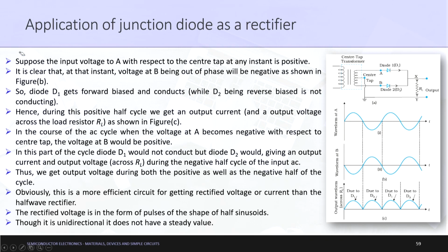So, basically what was happening till this point was that in the upward part it was positive, and if it is positive in this part, it is negative in this part. The voltage is negative in this direction, that means it is forward bias in this case, and it is reverse bias in this case. Correct. Then the next thing which we understood is that this was till the first cycle. So this was the first cycle, and finally what we got was this cycle.